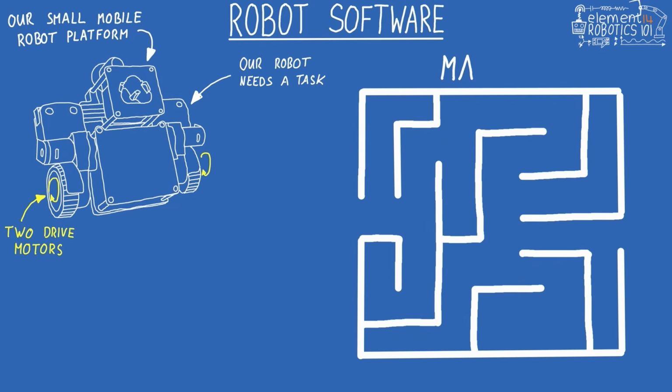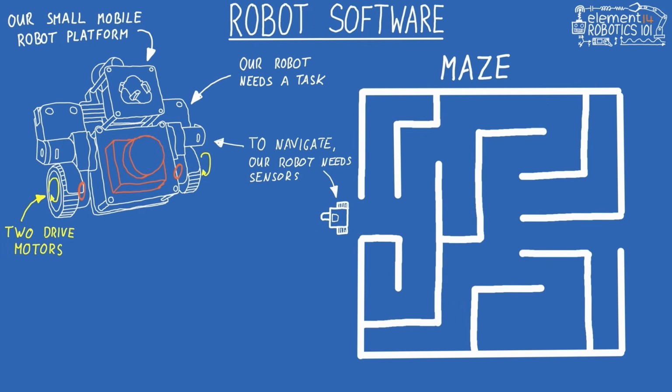To pull this off, the robot needs some sensors to figure out where the obstacles are. For example, we can use 2 wheel position sensors called encoders so we can measure the robot's position and speed, and a 360-degree LiDAR sensor to measure the distance to the obstacles.